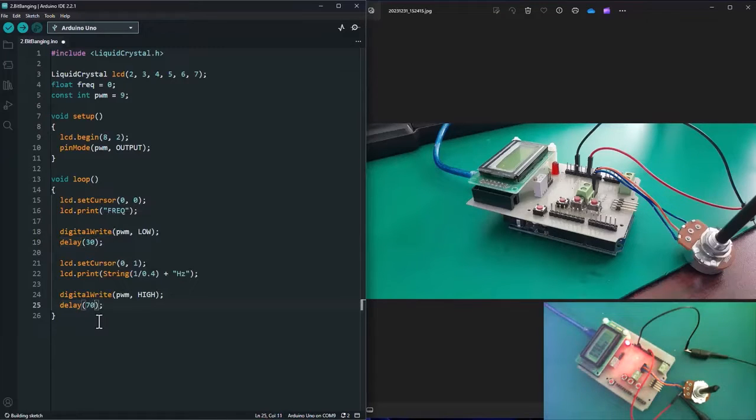Now this is going to change the frequency of the PWM signal because now it's only a 100 millisecond period, and 100 millisecond is basically 10 Hertz, which means it's slightly faster. But now we're going to have a positive width of 70 millisecond and a negative width of 30 millisecond. Now let's go ahead and load this into our Arduino board.